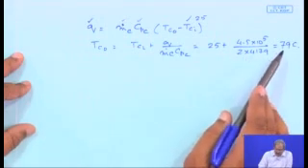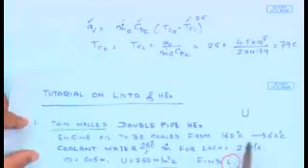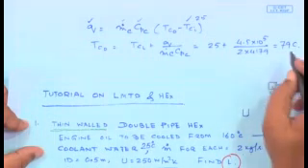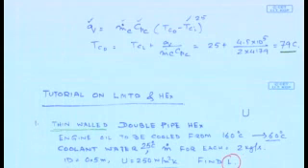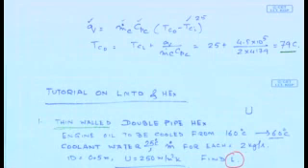One thing I would like to bring to your notice over here is that the outlet temperature of the engine oil is 60 degree centigrade, whereas the outlet temperature of the coolant water is 79 degrees centigrade. Now, what does this tell us? Here we see that the outlet temperature of the cold fluid exceeds the outlet temperature of the hot fluid.